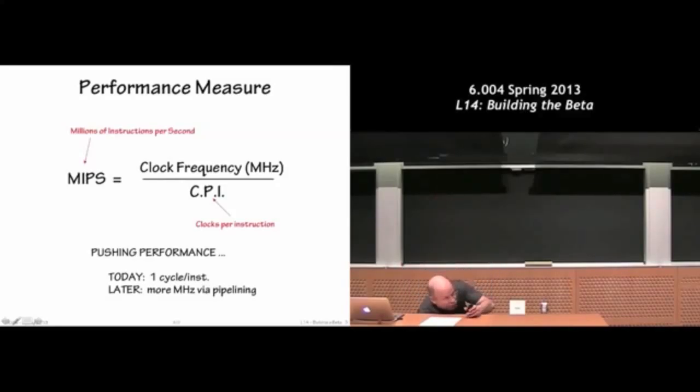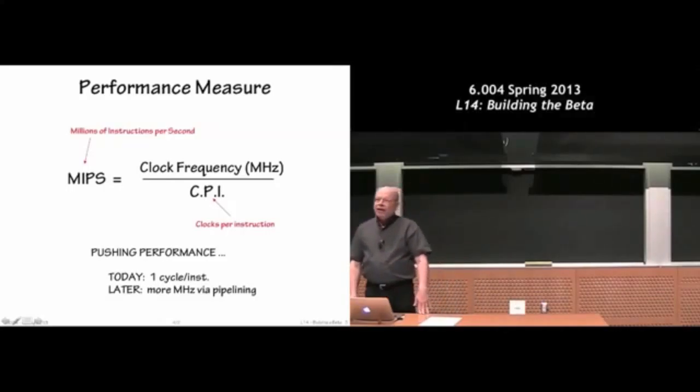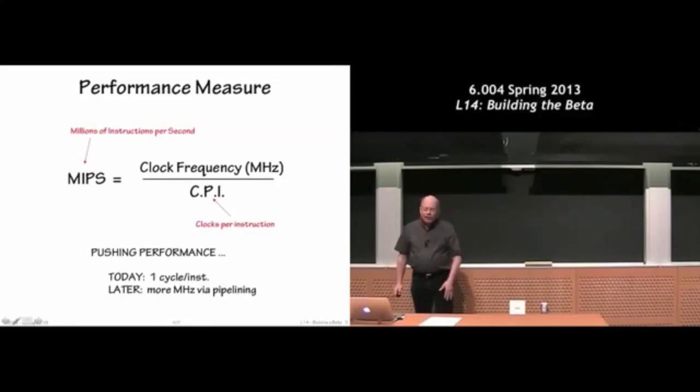And then we're going to try to get the best performance possible, although we're not going to spend a lot of time on that today. Right at the end of the course, we'll come back and talk about increasing the clock rate by taking our big, single-stage design, a fancy finite state machine with logic and a set of registers, and pipelining it so we can get the throughput up. The machines in your laptops have a 20-some-odd stage pipeline that they're executing instructions in. So their clock rate is about 20 times what they'd be able to achieve if they didn't use the pipeline at all. And that's part of what makes your computer so fast.